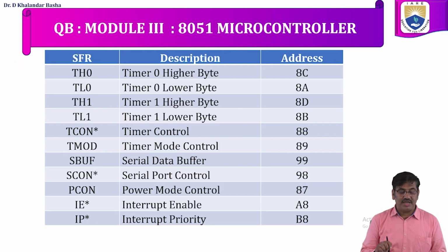Few more SFRs we are having. For timer 0, for placing the count, TL0, TH0, timer lower byte and higher byte. Similarly for timer 1, TL1 and TH1. For using the timers, we have two corresponding SFRs, timer control and timer mode. For serial communication, 3 registers we are having, SBUF serial buffer, SCON serial port control, PCON power mode control.